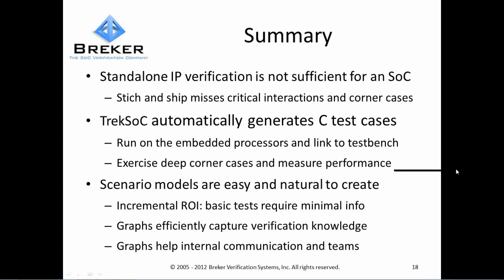So I think with this, you can go after quite deep state in just how the IPs can interact. But the real deep state is coming not from the individual iterations to the graph, but the fact that we're able to schedule that work concurrently across multiple CPUs and create a lot of traffic on the fabrics and on the memories. And just by hammering the chip hard, we find ourselves in the deep state cases, right? I mean, it's sort of a difficult question to answer explicitly. You're right, we are not probing into the design to say, hey, we're watching this particular bit and this bit tells us to go do something.